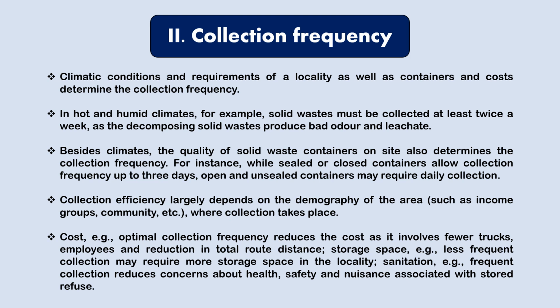Next, the quality of solid waste containers on site also determines the collection frequency. If we have closed or sealed containers, then we can collect the waste material with a frequency of 3 days.